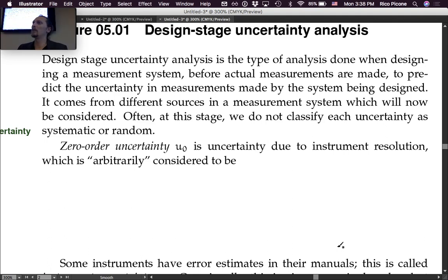And then when we describe the uncertainty, we say, oh, okay, well, we know within 0.1 kilograms what the weight of this is. That's our uncertainty. So we're very confident that it's 1 kilogram plus or minus 0.1 kilograms, for instance. We have a 95% confidence or something like that. So yeah, it's subtle, it's just two sides of the same coin. The error is on the device side, the uncertainty is on our side as the person who's measuring something with the device.